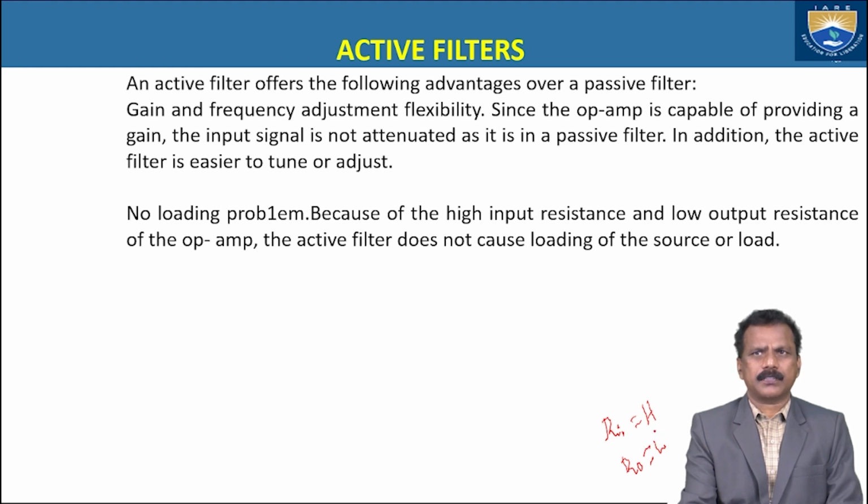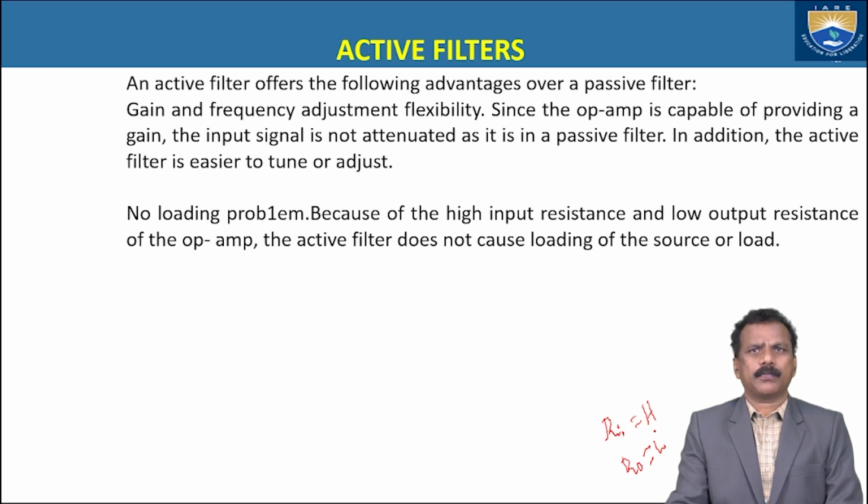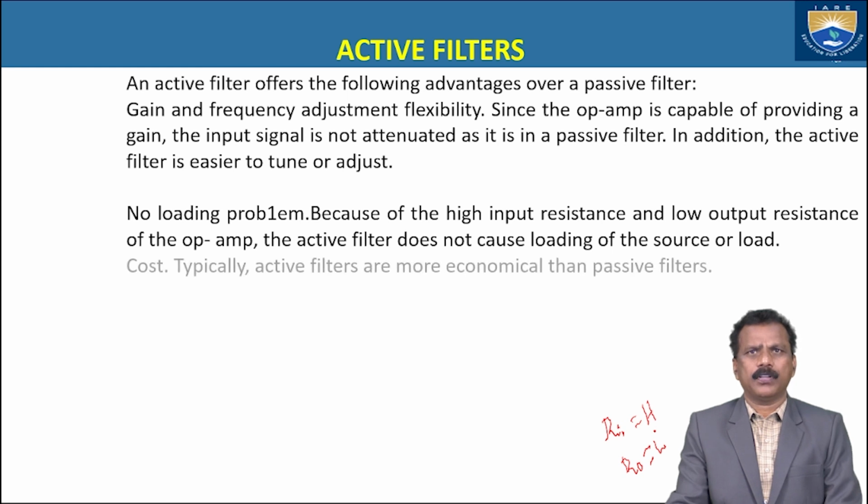The active filter does not cause loading of the source or load. So that means this is the no loading problem because of the high input resistance and low output resistance of the operational amplifier.